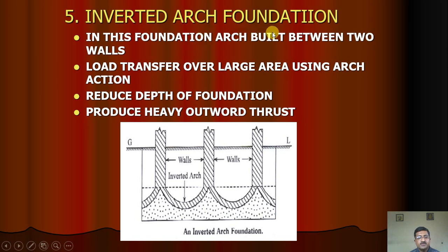Inverted arch foundation: in this foundation, an arch is built between two walls, load is transferred over a large area using arch action, it reduces the depth of foundation, and provides heavy outward thrust. But nowadays it is not used. It is obsolete now because other foundations are available.